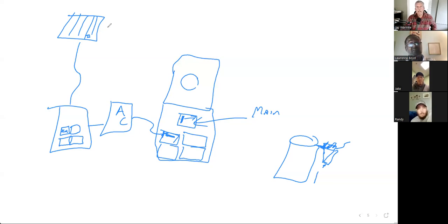So if I'm designing a system like that, even let's say I'm putting a 5 kW system up here, it's only going to have, let's say, 5 kW, maybe it's got 15 amps. Let's say that's my power output in amps. Well, if I'm running wire down to the system, in this case, I would run wire that could handle 20 amps, even though I'm only going to be running 15, because I might expand this in the future and I don't want to have to pull new wire. It can go to a maximum of 20 amps. So coming in here, I could do 4 of those, but for right now, I'm only doing 1.